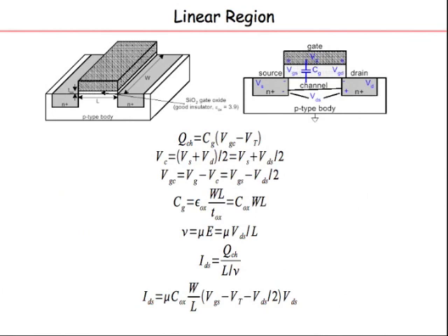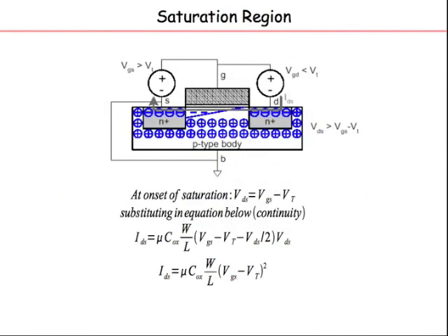And this model actually was working well till about maybe 20 years back. It is what is called the long channel model. When the transistor channel lengths were a few microns, it worked well, and you could describe the transistors very nicely using these simple equations.